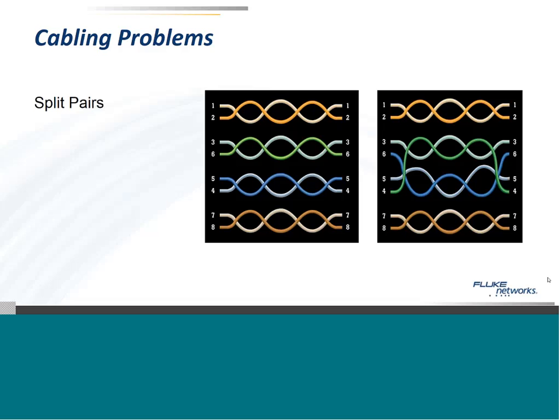The only way to exempt the cabling, or to understand that it's not the problem, would be to test it with a high-end certification tester as opposed to a low-end type tester. That's a very good question. In fact, that brings up one I'll talk about.